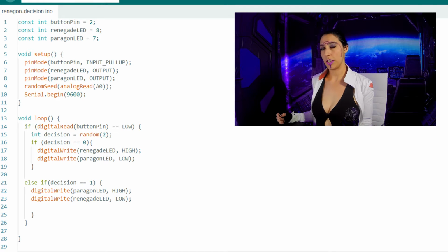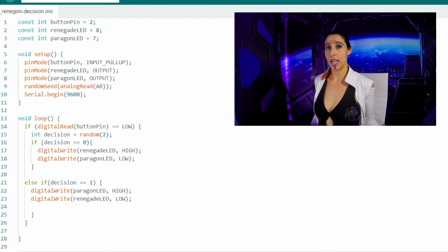You can do a few different things with the random seed function. This function initializes the random number generator, causing it to start at an arbitrary point in its random sequence. The sequence is always going to be the same, but long and random. The parameter is the seed, which is a non-zero number that initializes this pseudo-random sequence. If you want a pseudo-random sequence to repeat exactly the same, then you can put a fixed number in as the argument. What we want though is some hardcore randomness.